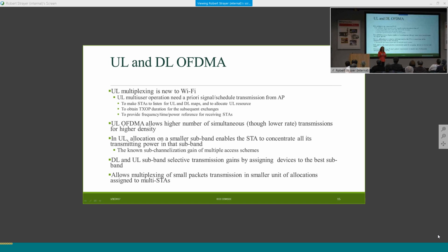But the good thing is that it allows them to stay synchronized. So if on the trigger frame they synchronize and correct their timing offset and frequency offset, it stays valid. 16 microseconds later, it stays synchronized when it is received at the access point. The access point still needs to do the per-user phase tracking, for example, to handle any residual error. But that should be okay because the access point is a powerful, expensive device. I think I covered all of this.